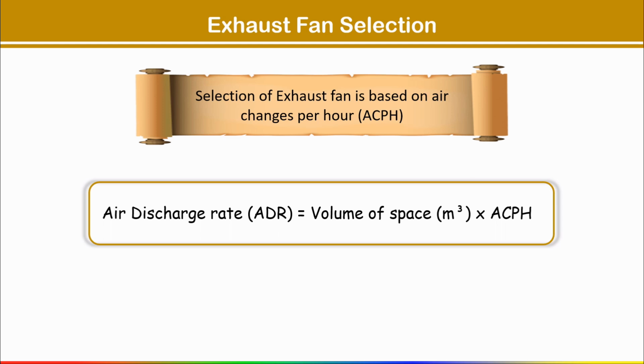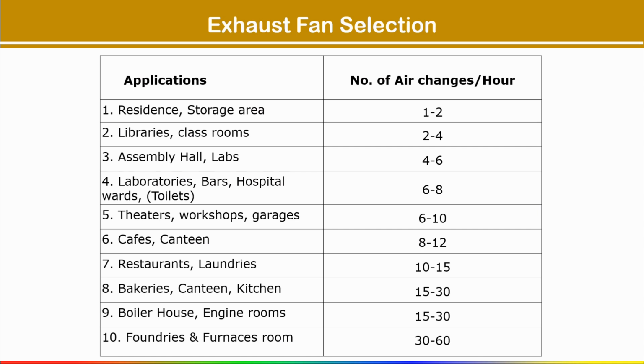Now the question is from where we get the ACPH value. So remember, as per ASHRAE, they have given the ACPH value for different spaces. Okay, I will show you. And remember, whatever air discharge you are calculating is in which unit? Meter cube per hour.